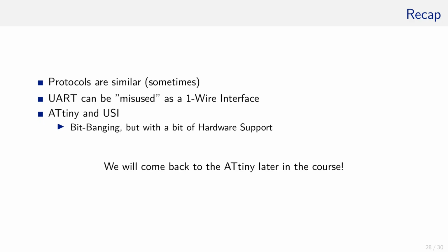Control and special cases for each of the protocols then need to be implemented in software. Hence, USI is a bit like bit banging, but with some hardware support.